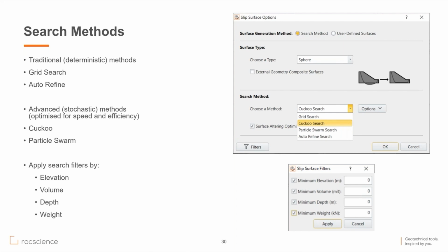Whatever modeling software you're using, I think it's important to have an understanding of the failure mechanism before you start modeling, so that way you can then select the most appropriate analysis tool. So yes, that would include an understanding of where a weak zone or weak planes are located, and if it is back analysing a failure, if you do have survey data from the field.